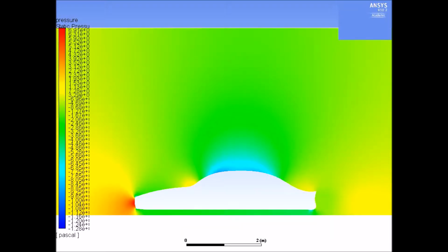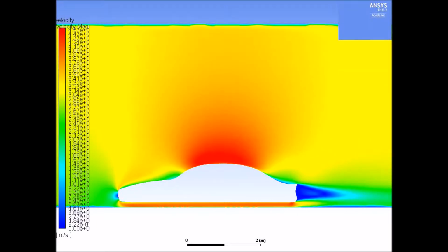So a reduction in drag will actually reduce the fuel consumption in any sort of vehicle, and it also increases the safety and durability of different geometries that are subjected to high velocity fluids. It can also reduce noise and vibration, just creating an overall better system. The main way engineers can reduce drag is by redesigning or overhauling the geometry of whatever object they're dealing with in order to allow fluids to flow over the object more easily.